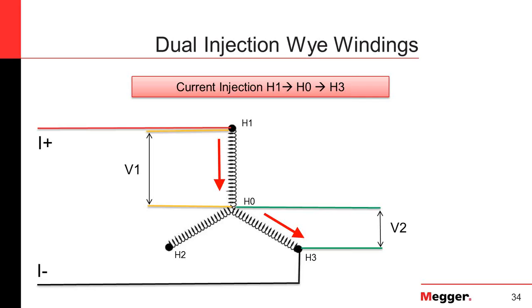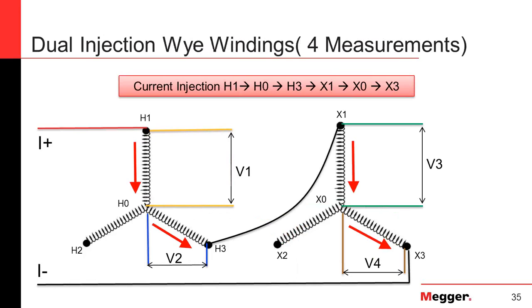And so here are just other examples. In this case, we have instruments that measure 4 windings, so we can measure all 4 windings at one time. And if there are taps on one side, we simply run all the current through, and then we change the tap, OLTC, and then record through, wherever we decide to start and finish.